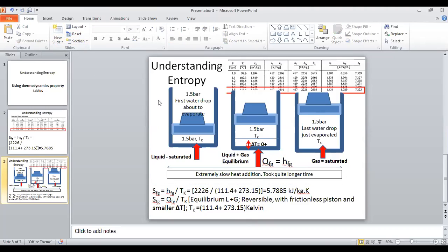So this is a very important slide. You should note that there is a moving part: in this system there is a moving piston, which adjusts the volume as the liquid expands when turning to gas. To adjust the volume, you have to have a variable system volume, and that is achieved by moving this frictionless piston upward when you are putting energy into the system.